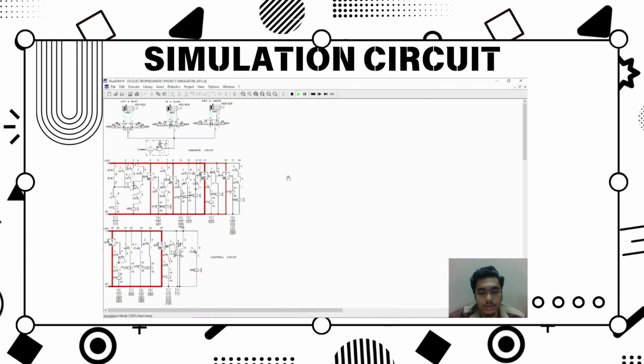When I run the simulation without pressing any push button, -SF1 and -SF2, solenoid coils -MB1, -MB3 and -MB5 will be de-energized, and due to the dominant spring return DCV, the right switching position is activated. Compressed air at port 1 will be shut off, and air will not be allowed to flow through, and double acting cylinders -MM1, -MM2 and -MM3 are in fully retracted position.